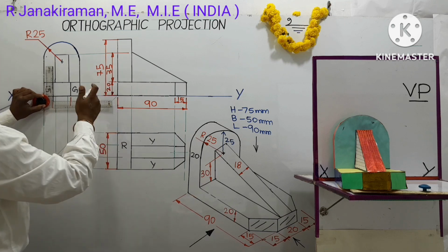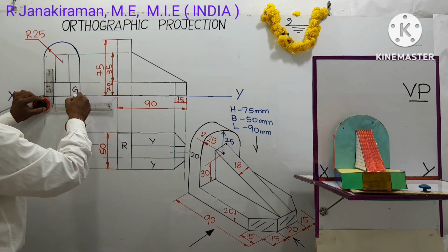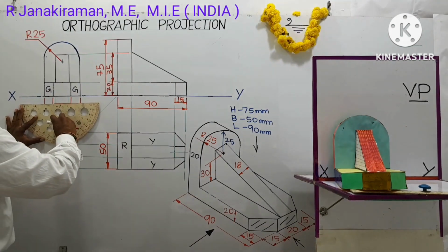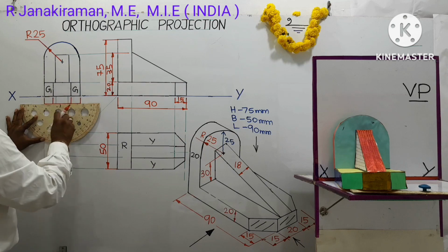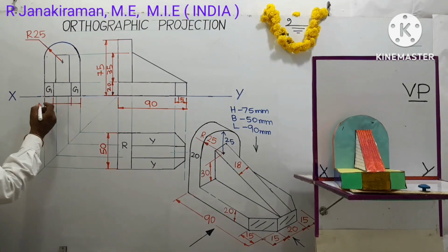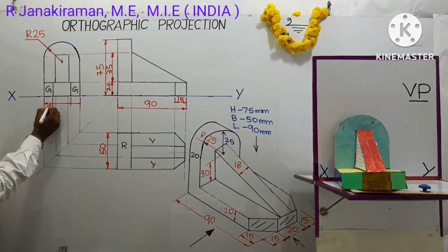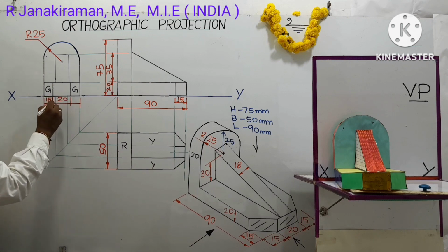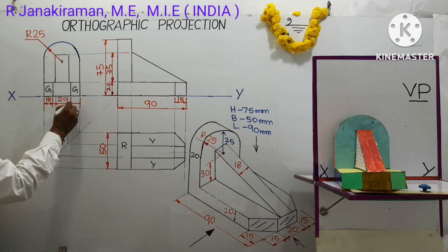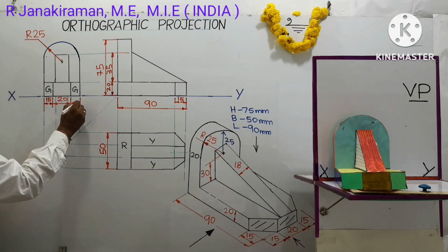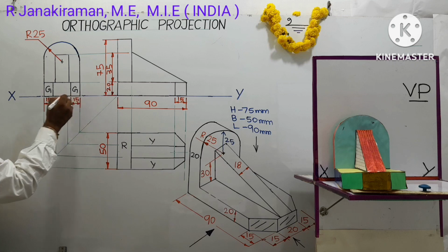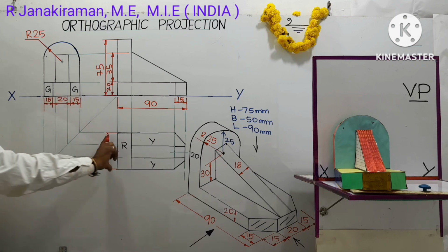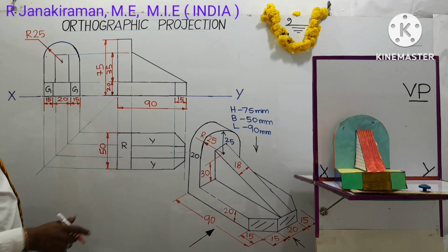Check whether the scale is perfectly horizontal or not. You can complete this dimensioning work using the drafter scale itself. So this is the horizontal distance along the breadth of the object: 15, center 20. Put arrows at both ends of this dimension line, shade them and write 15. So 15 plus 15 is 30, plus 20 will be 50 mm. It's the overall breadth of the object seen in the side view, called the right side view.